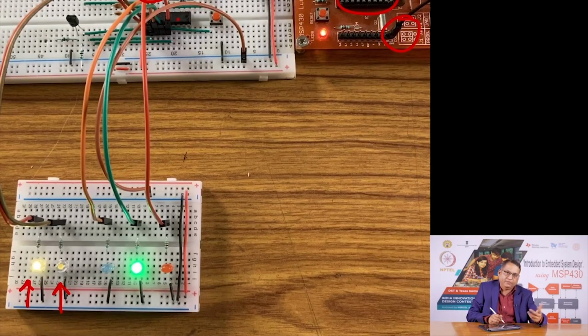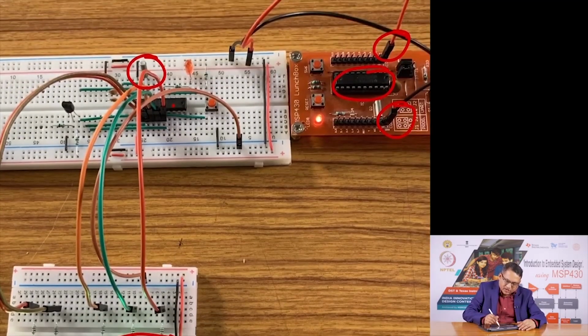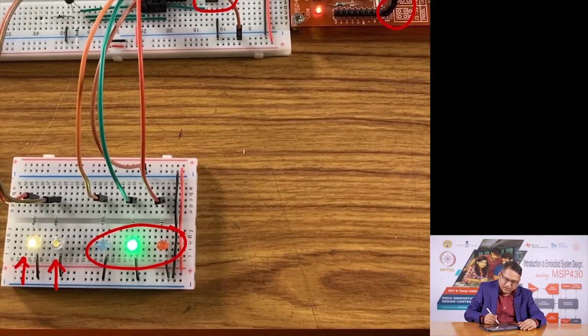This will turn on the moment power is applied, and these are the 3 LEDs which indicate the source of reset, whether it is power on reset, whether it is user reset. This is the user reset pin, the switch, and the third source could be the watchdog timer. So, I recommend that once you have programmed your microcontroller in the lunch box with this code, take it out gently, insert it into the breadboard using the crystal oscillator and other stuff, connect these LEDs and see how the microcontroller is able to find out the source of reset.